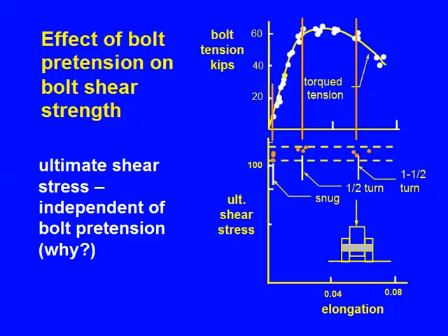But somebody puts his bolts in 1.5 turns, which is not a permissible value, by the way, but he did. He felt energetic that day, and he put on 1.5 turns. And you say, wow, he's destroyed everything. Well, as it happens, there's still a very high pretension force in there. It's about, I don't know, 59, 58 or something like that.